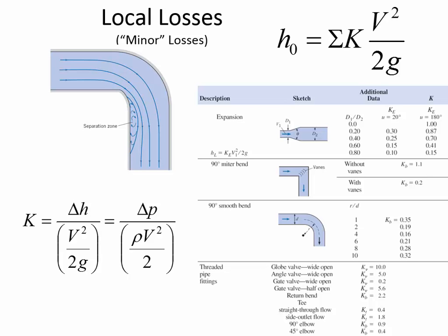And so you have to know in a system, whether it's a house or inside of the streets where the water is flowing underneath the roads, you have to know what is there. There may be a T, or the water is going around a curve in an elbow. And so think about the case of what if you have water going on a curve. So a pipe suddenly changes direction. There's going to be a lot of turbulence when the pipe suddenly changes direction compared to if it was more gradual. And so if the water is changing direction gradually, it's causing less turbulence inside of the pipe section, and the K value will be lower.